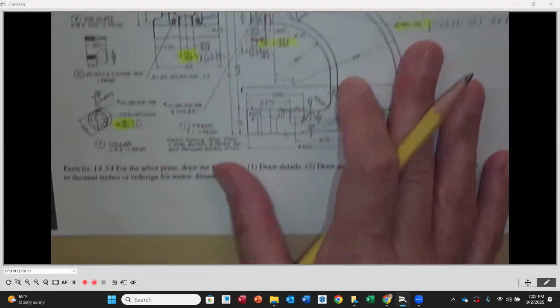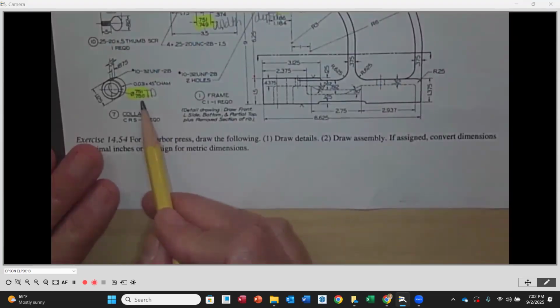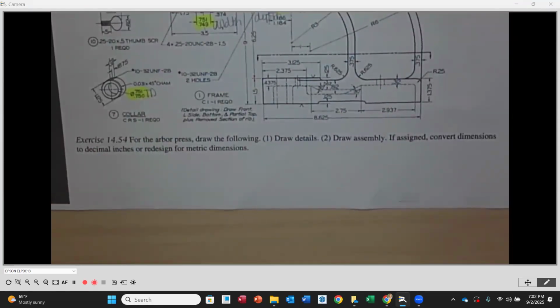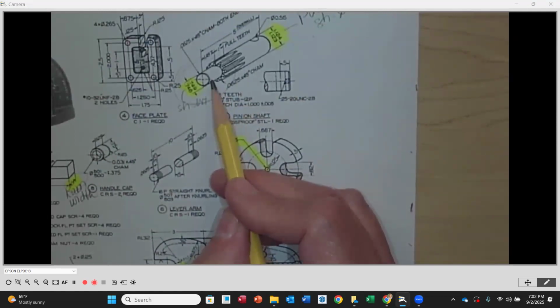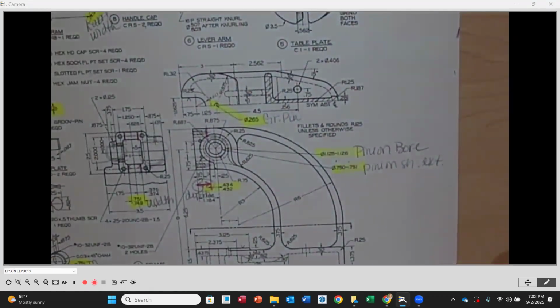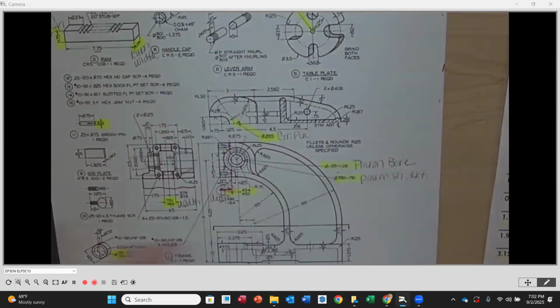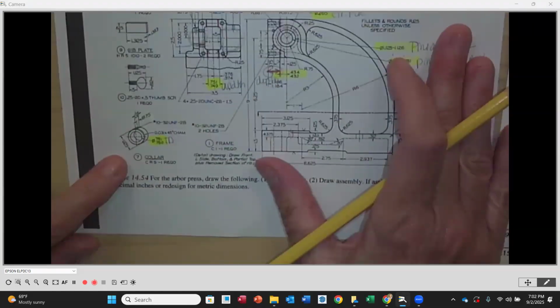Now, in that collar, as we saw in the video earlier, there's a set screw that's going to lock it, or keep it on the shaft. So you are going to do the fit on the ID. Again, it's giving you limits already. Ignore those. Just go nominal size. In this case it is 3/4 of an inch. It's going to fit over the end of this shaft extension, and you're going to pick a fit that's appropriate for that. Okay. Clearance or interference? What do you think? Probably clearance, but now you've got to think, do I want that to be a sloppy fit or do I want it to be a relatively close fit? That's something you have to think about.